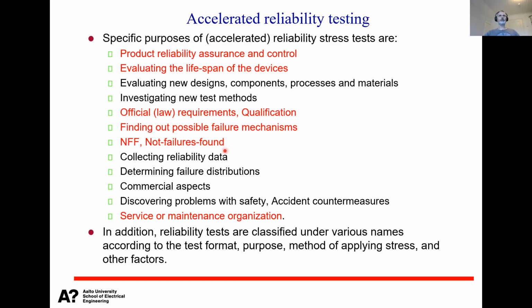So by using these kinds of tests, for example, you not only do the electrical testing on your test bench, but you do the same electrical testing by putting the whole system in the furnace and adjusting the temperature up to 60 degrees or 80 degrees or whatever. So you heat it up, and then you might find the actual problem.